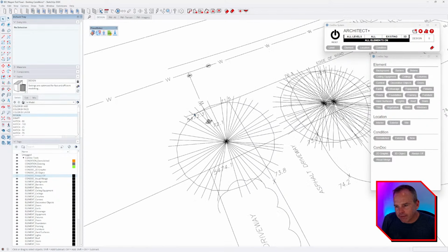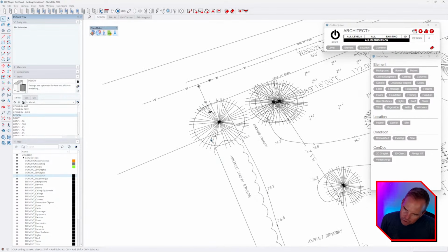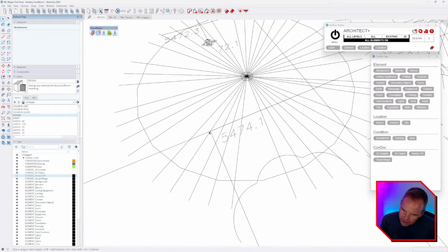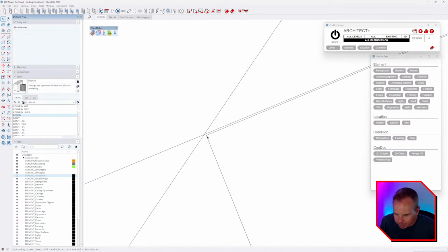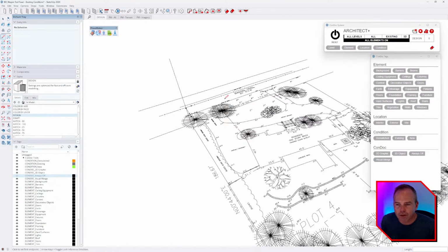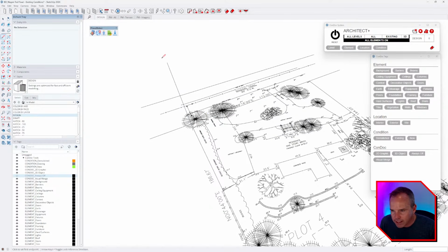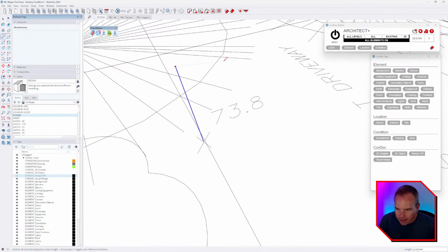All right. Then I'm going to zoom way in here and look for the corner. We'll call this 74.1. As I zoom in, there's my corner. I'll tap the up arrow key and type 74.1, enter. Now there's a line that exists at 74.1, and what we're going to need is that endpoint up there. Like I said, this is going to get a little tedious. I'm just going to work through here, and we're going to do 73.8 like that.